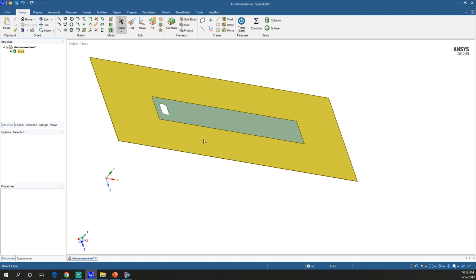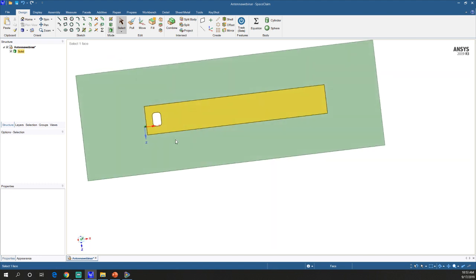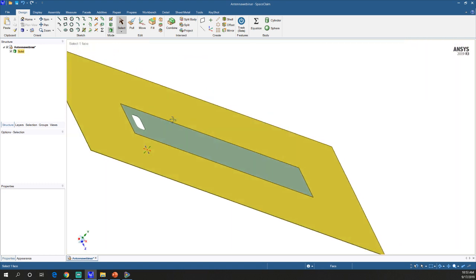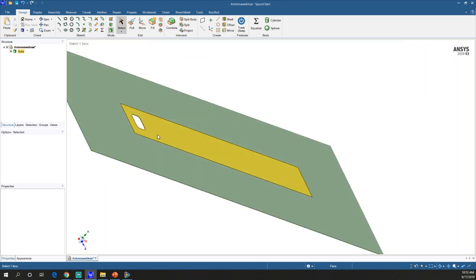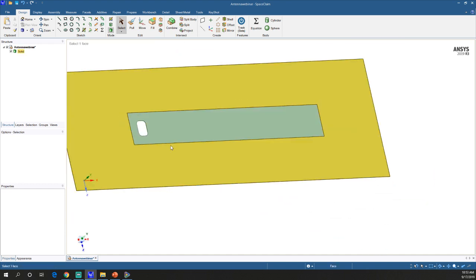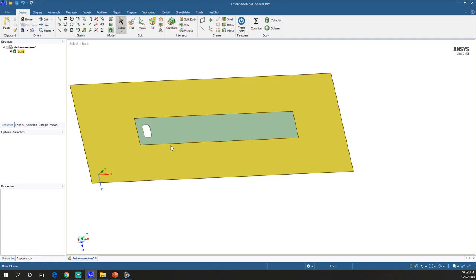So start with a 2D analysis. Pretty much no matter what you do, the first model should be a pseudo 2D. I don't care if you're doing a solar panel or a building or an antenna, right? Start with a 2D so you can quickly, in an hour, go through 6, 7, 8 different settings, make sure that the results are reasonable, and then go for a large model.